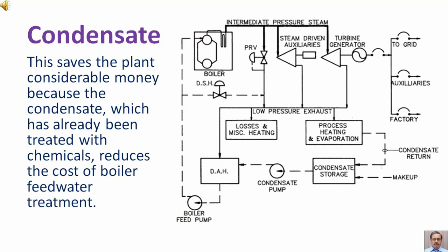This saves the plant considerable money because the condensate, which has already been treated with chemicals, reduces the cost of boiler feed water treatment.